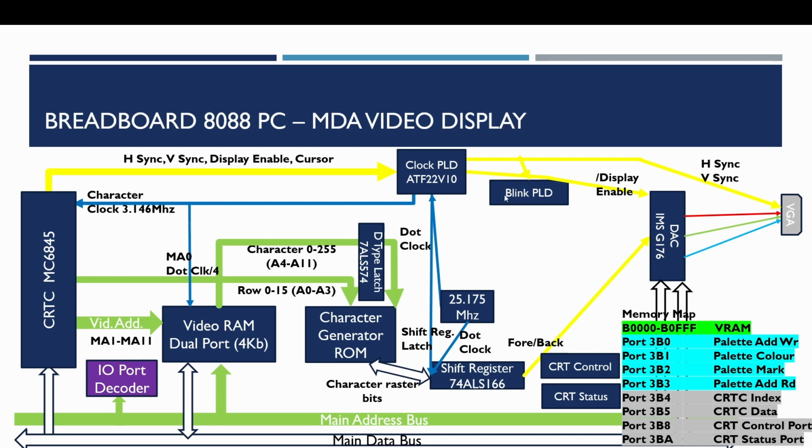In this video, relatively simple steps. We're going to be adding a special programmable logic device for producing the two clocks needed for the blinking of the cursor and the blinking of the characters, and also the CRT control and status registers, which appear in the memory map or the I/O port map on the right hand side here. So have a quick review through the PCXT schematic diagrams which have been annotated, which we covered a number of videos ago.